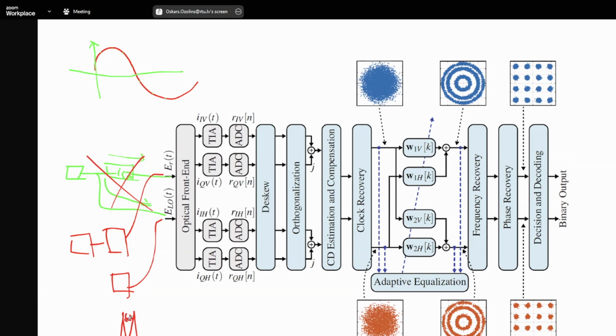If there's a frequency difference, then most likely these are heterodyne systems. And this frequency difference should not be too large. It should be basically smaller than the available bandwidth in your ADC. In practical systems, this frequency difference is maybe on the order of megahertz.